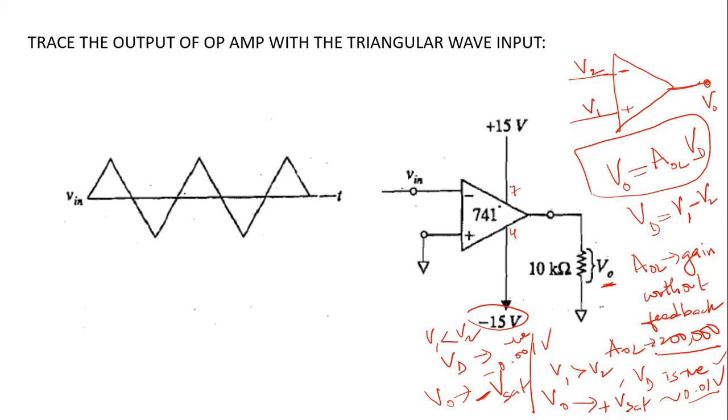So in this simple circuit shown here, the voltage at the non-inverting terminal, which we denoted as V1, is connected to ground. Whenever you have a triangle like this, it means a ground connection. This is 0 volt. So your V1 is 0 volt. And the voltage at the inverting terminal, which we call V2, is now connected to Vin, the input signal.